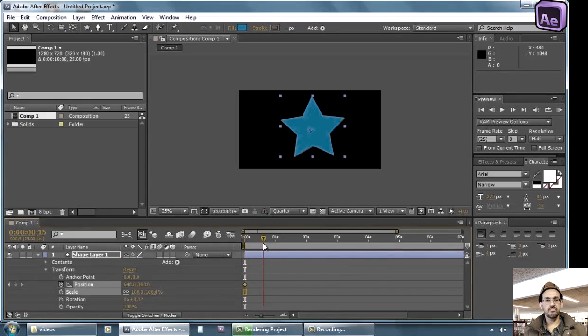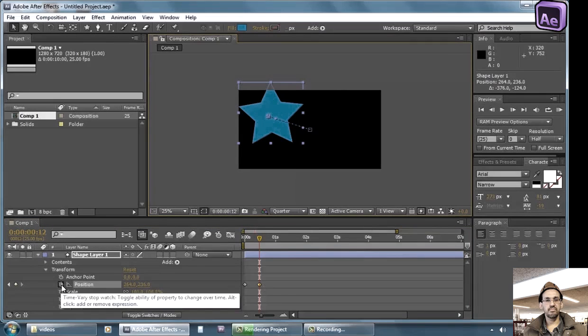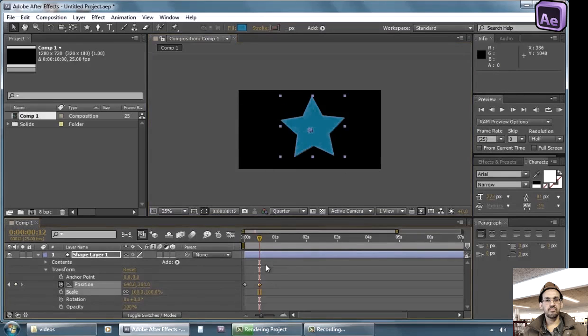And if we move forward on the timeline, we can mark that position by clicking this diamond shape keyframe mark, or automatically. Let us first remove this keyframe by moving the shape to another position. If the stopwatch has been activated, the keyframe will be automatically marked for that point.